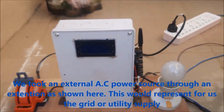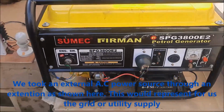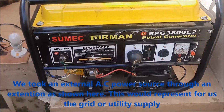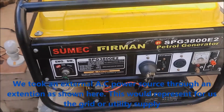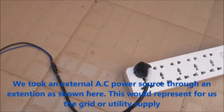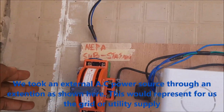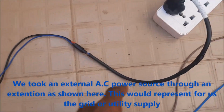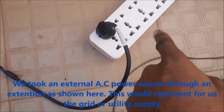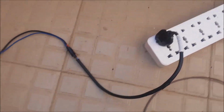Now, let us get a better functioning backup generator and do a proper testing. Remember, we are using this setup to test the automatic switching of the design from utility power lines to the backup generator power lines when there is an interruption in the utility grid. The socket extension serves as the utility grid supply. We connected them as such. We are sending and receiving SMS signals through the GSM module with its antenna showing here. The light bulb represents the household appliance.